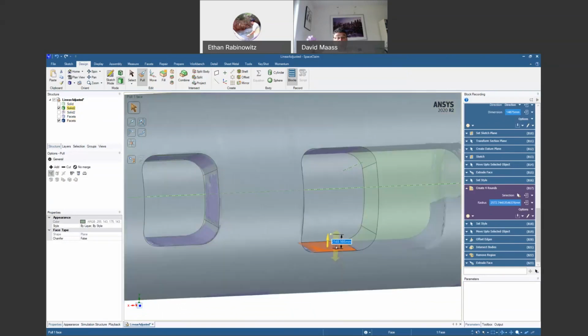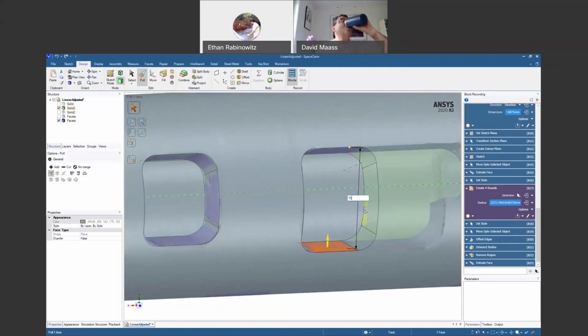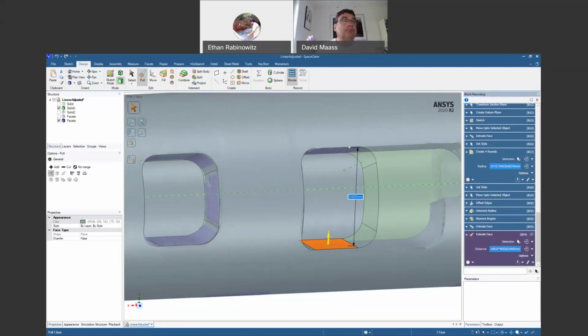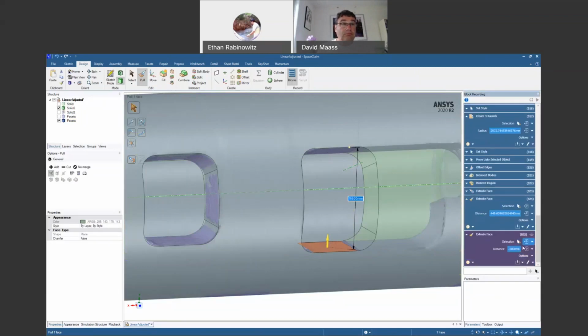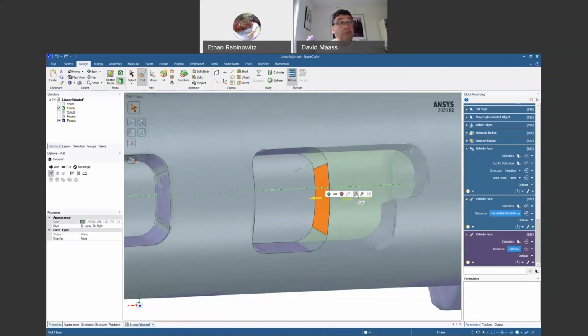So if we want this one to have its own dimensions, what we could do is pull this face, set up a dimension to somewhere else, and then here if I just edit the value of it, even by like, I should have done like 1550. That saves it as an easily editable dimension here. Interesting. So for some reason it's storing it as a change and not as that ruler, even though before it did. So I think that's something I just need to look into. But if we were to sketch it out and parameterize the sketch, then that is definitely the most direct way to be able to edit this. But this is a nice little shortcut if we're going to have similar things.